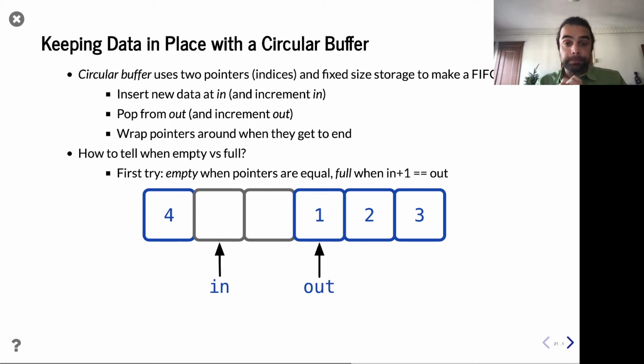So how does that work? Well, we use something called a circular buffer. This is a general computer science concept, used also in systems. The idea is you have some amount of memory or registers, whatever, and you use two pointers. You insert at one pointer and you remove at another pointer. Here I'm saying the word pointer like in software, but you can imagine in hardware within a mem, this could just be an index, right? It's kind of tracking where it is. If I want to insert new data, in this particular case someone inserted 1, 2, 3, 4 in order, so the next insertion is going to go here. And when they want to DQ, they simply read an entry and then, of course, increment this pointer, right?